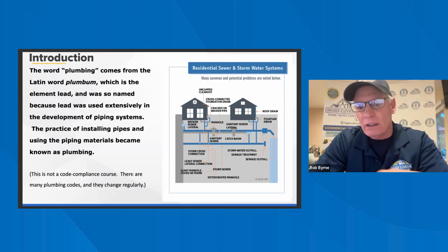The inspector shall report as needed in correction any deficiencies in the water supply by viewing functional flow in two or more fixtures to see how the pressure is. Deficiencies in the installation of hot and cold water faucets. You always want to make sure that hot is on the left, cold is on the right.